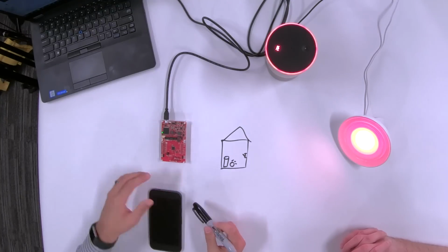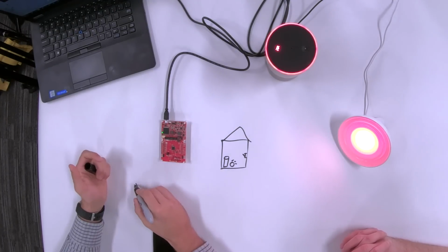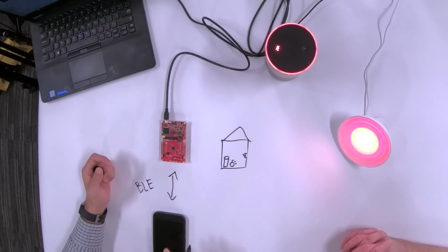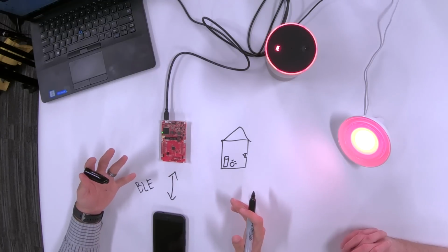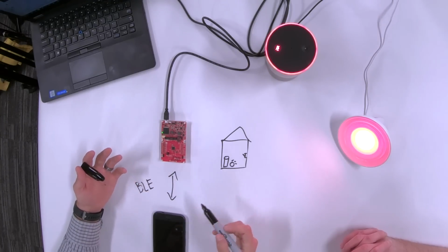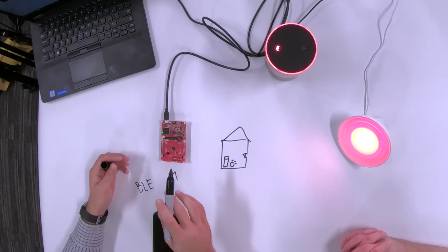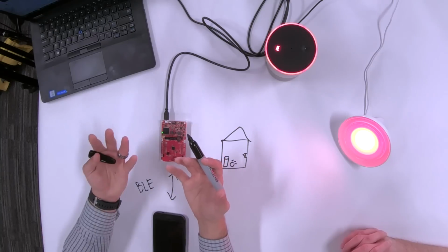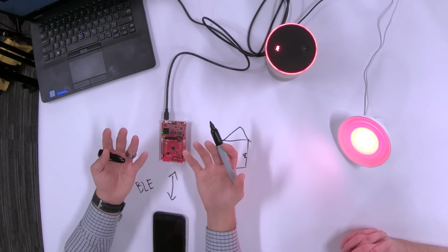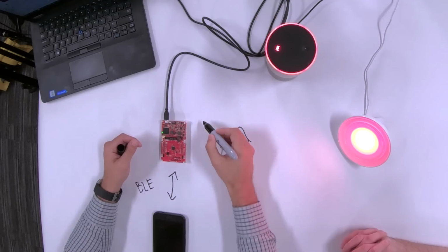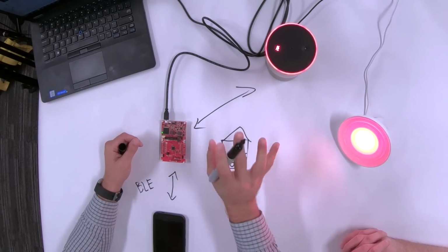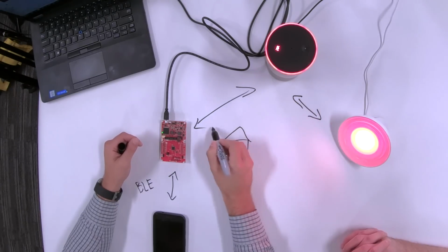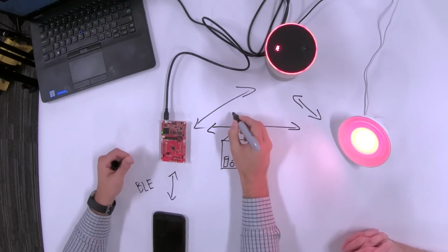I'll be using my phone, and so we'll have a BLE connection right here, where I'll be reading BLE characteristics, very general characteristics, so you don't need anything special. And those characteristics will be able to talk to the Zigbee side of the stack. So that's the other stack in the DMM. You have the Bluetooth, or the BLE, and the Zigbee. Sure. And through Zigbee, we will communicate with the coordinator and the Hue light here. All right. This is all Zigbee.